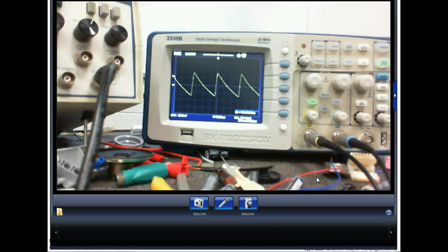And what determines the amount of ripple? Well, the amount of ripple depends on the frequency of the pulses. And then, of course, the other thing it depends on is the size of the capacitor and the current required by the load. So we'll show you how to calculate that. Hopefully, by the time you get out of here, you'll be able to build your own power supply.